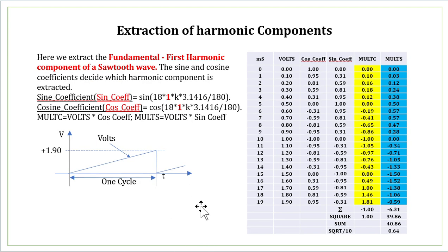So now we take a different kind of waveform. This waveform is not a symmetrical waveform. So across this midpoint, it is not the same. So in case of a sine wave, it used to be the same over the entire cycle. You got it showing like this. And this is very much an unsymmetrical waveform. Now, this waveform will have even harmonics also.